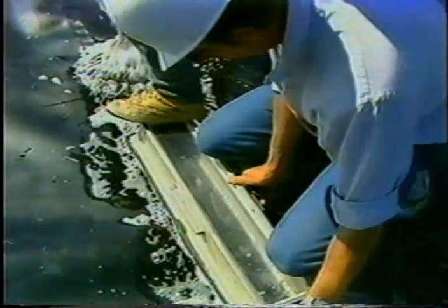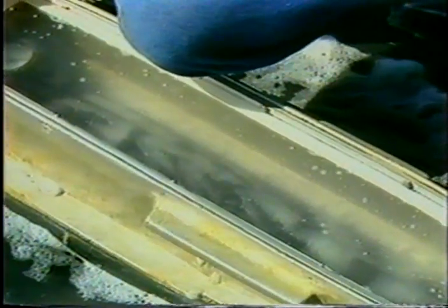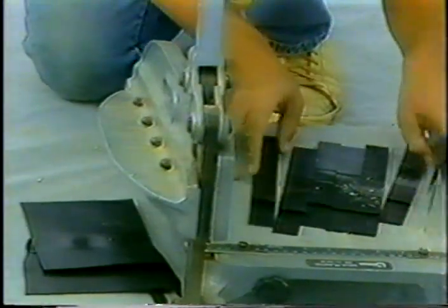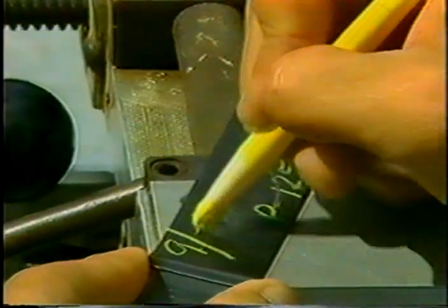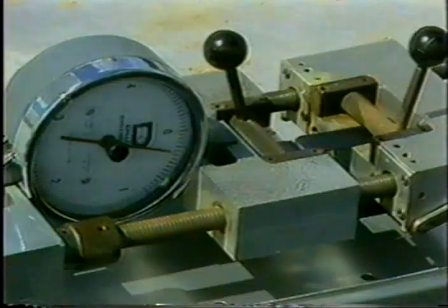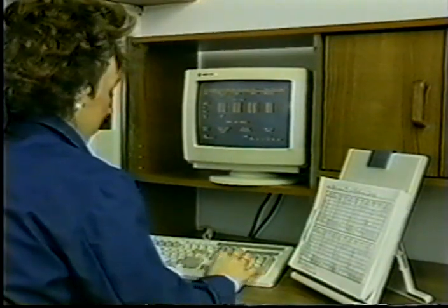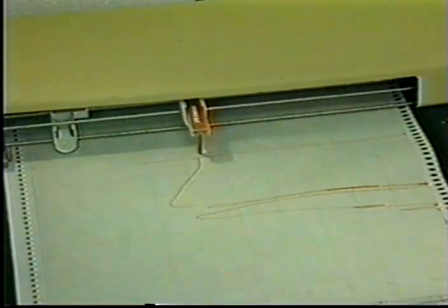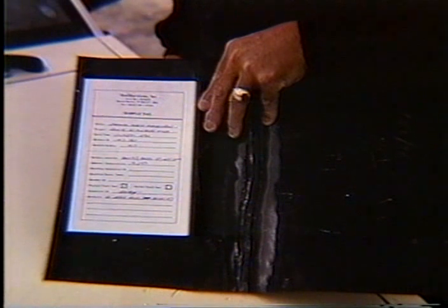These non-destructive forms of seam testing, carried out on site, evaluate the continuity of seams, but not their strength. Their strength is assessed by destructive testing, where samples are taken from actual seams. The seam samples are then divided into parts. A part is immediately tested on site. Part is sent to an independent laboratory. The peel test is one standard lab test for seam strength, and the shear test is another. Part is given to the manufacturers. Finally, a part of the sample is retained in archives.